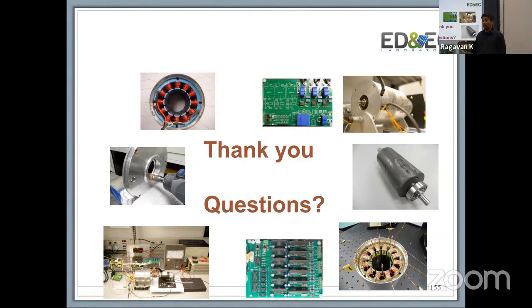Now, if you hurt the magnet and created a massive hotspot, then you have to replace the winding and work through the magnet. That can happen, but normally you should be able to identify the fault one way or the other before it gets to a place where you start damaging components other than the winding itself. Is that reasonable? Okay. Any other questions?